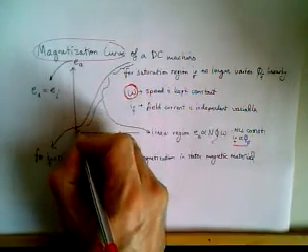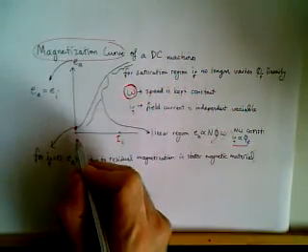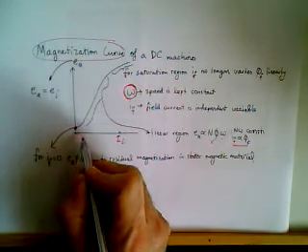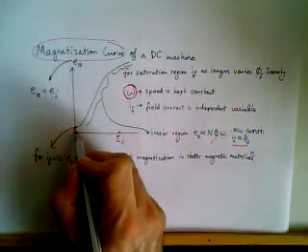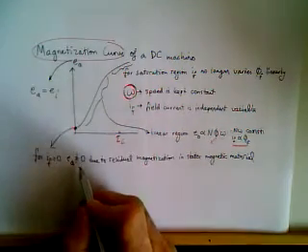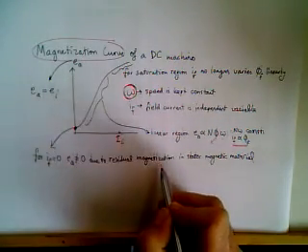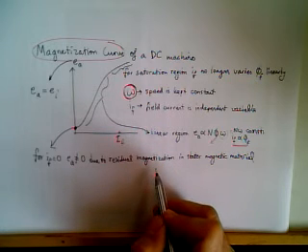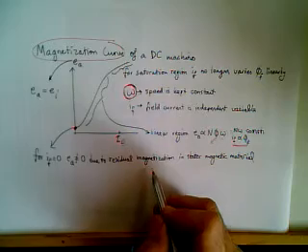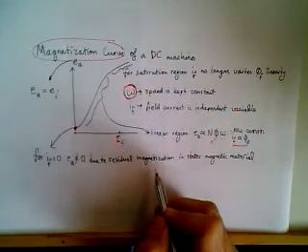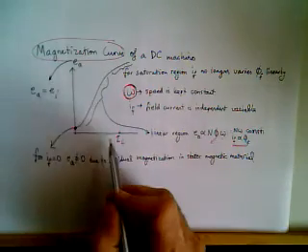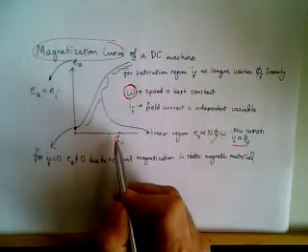This point is not the origin. When we rotate the machine under no excitation, we still obtain some induced voltage. This is due to residual magnetization. Inside the DC machine, the magnetic material has some residual magnetization, and it behaves like a magnet, although there is no electromagnetic current inside the machine.